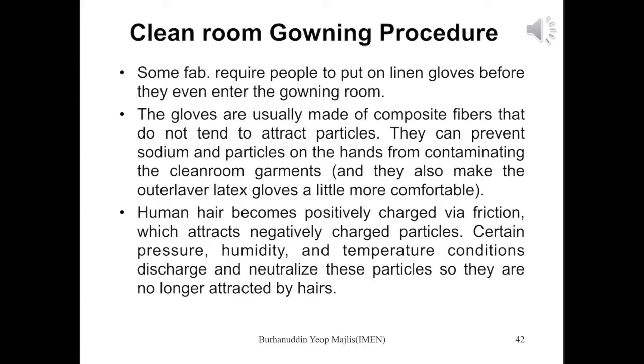Gowning procedure. Some fabs require people to put on linen gloves before they even enter the gowning room. The gloves are usually made of composite fiber that does not tend to attract particles. They can prevent sodium and particles on the hand from contaminating the clean room garment.